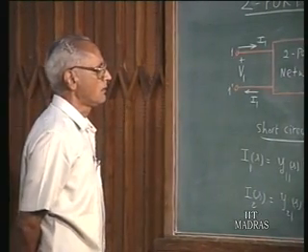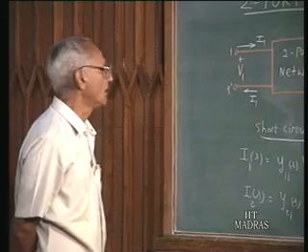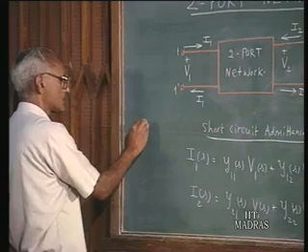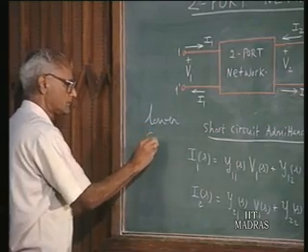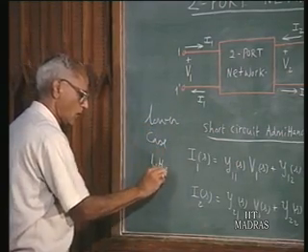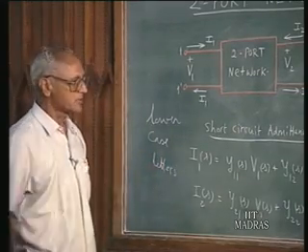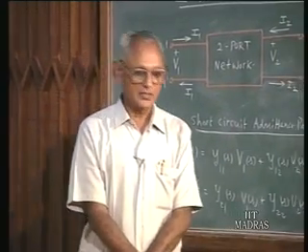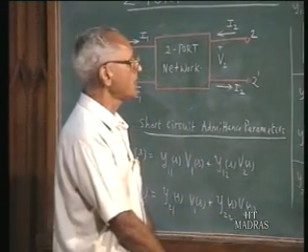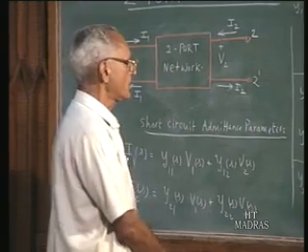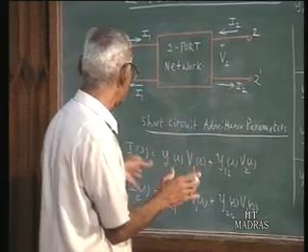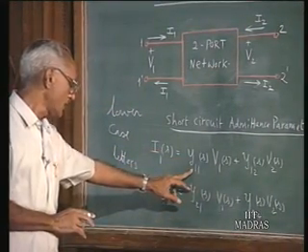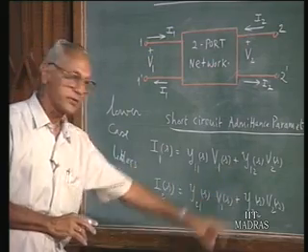Another point to keep in mind is we use lower case letters for these y's, not capital letters. Small y, and later on small z, because these are admittances defined under certain normalized conditions. The general admittances with other types of terminations use capital letters, but when used specifically for short circuit conditions, they use lower case letters. Therefore, you must keep in mind that y11, y12, y21 and y22 use small y's.